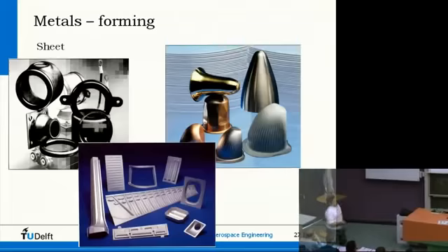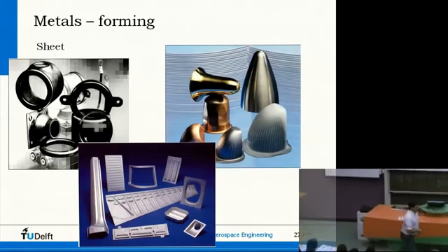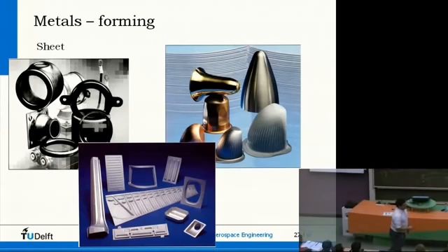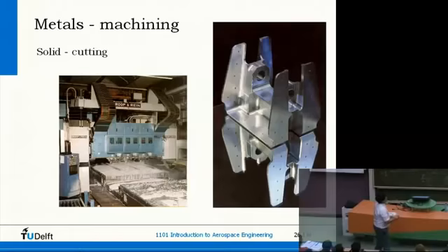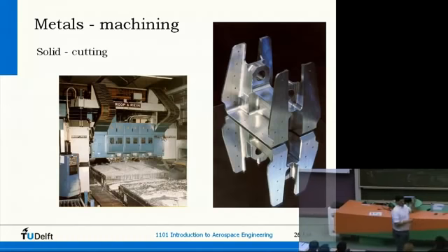How would the way of manufacturing affect the performance? Because in the end, it's a product. If you would cast a structure like this, the microstructure is different. And that can have an impact on, for instance, fatigue and corrosion. So from a corrosion or fatigue point of view, this could be better. Not always, but this could be better.